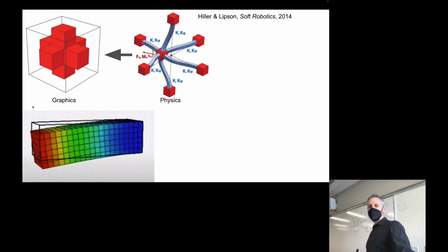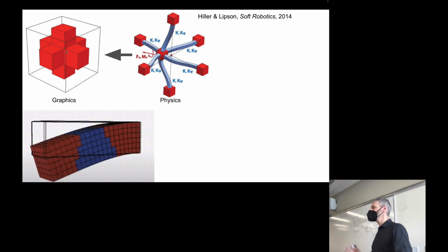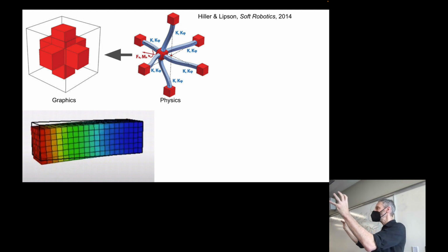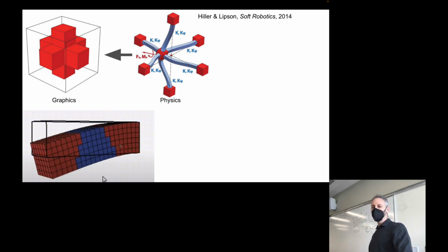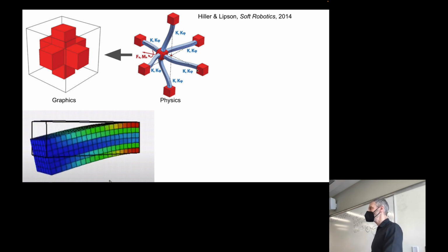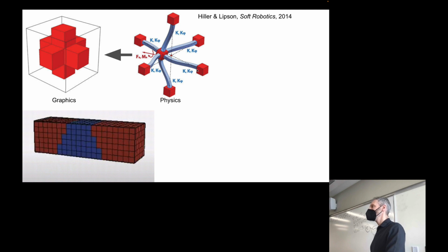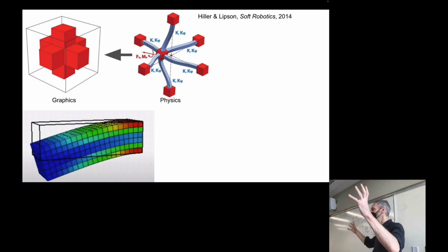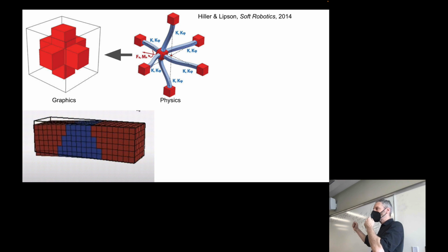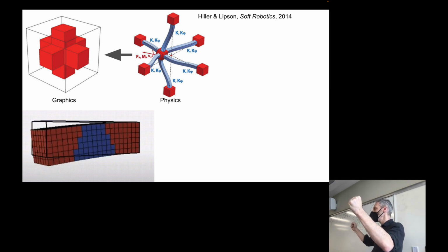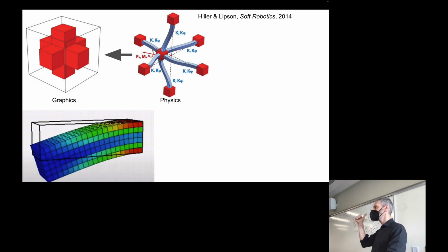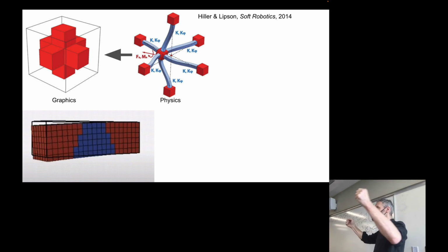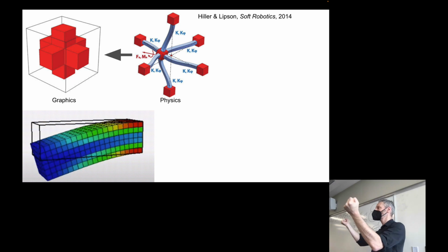How do we do this? Let's take our simulation up here of our 7 voxels, and imagine we take each of these 7 voxels, we leave them in the same place, we just shrink them a little bit. Hidden from view in the simulation, there are actual beams that are connecting neighboring voxels together. What is a beam? A beam like you would expect at the macro scale, so steel beams. You can think of this beam as a type of spring. So we've already talked about springs before. Springs have 2 values associated with them, stiffness and damping. Those 2 features determine how this spring resists being pulled or pushed away from its resting length.